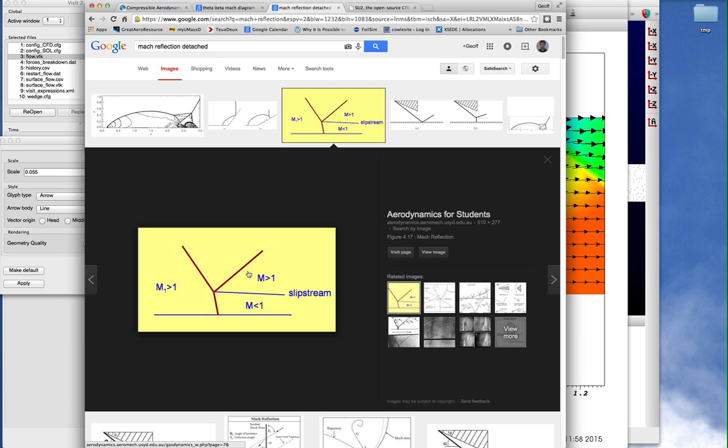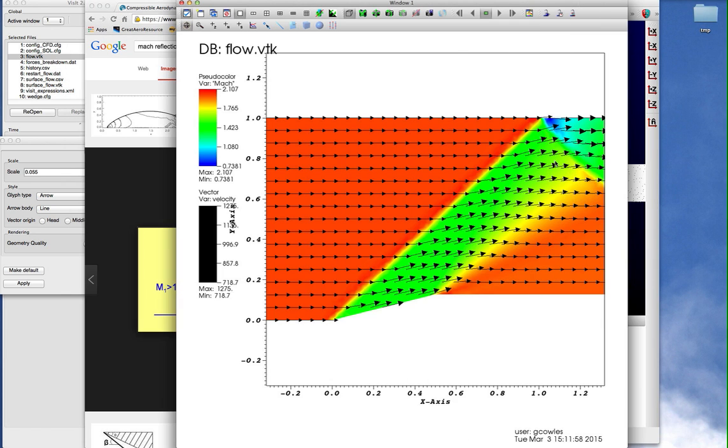And so you end up with supersonic flow here, subsonic flow here, and there is a shear layer between them, a pretty cool shear layer, which is barely represented here. So you have flow turning up, turning back, but this flow up here is going through a strong shock so that it is subsonic behind. So that's only in these conditions.